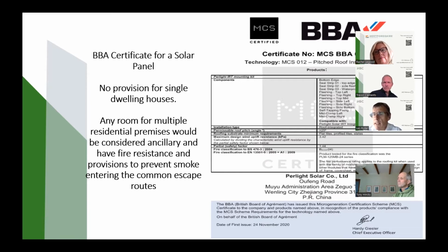They're generally staggered, and the staggered part of the flat roof is generally littered with either PV or air source heat pumps. And under those circumstances, all of the switch gear will then disappear through fire resistant constructions with the required fire stopping as those cables pass through the fire resistant constructions of the building and the service shafts.